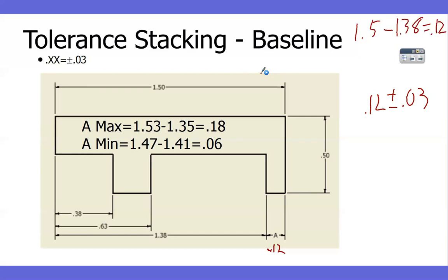Right? That's why drawings won't have all the dimensions. If they did, you wouldn't have any space for those tolerances to stack up. Try, but it's not always going to happen. You're going to get lazy and not brush out the chips, and it's going to be a chip stuck against your stop. You slide it over on the bandsaw. Now that piece is a little bit too short. Or you jam it in there, and because it's an angle cut, it digs underneath your stop. Now your piece is a little too long.